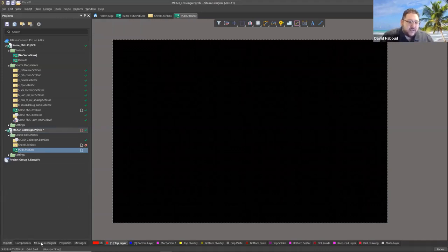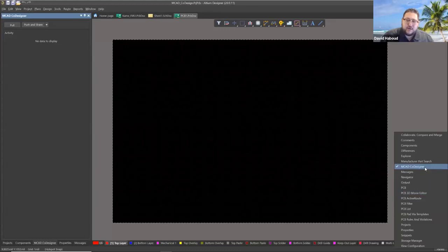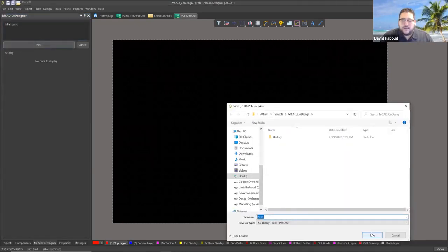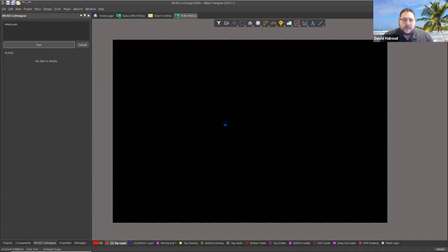Now that we have that done, I come over to the MCAD CoDesigner panel. You can go to Panels, MCAD CoDesigner if you don't have it up already. I'm just going to do push. If I do push and share, I can specify someone's email that I want to share that design to. But I don't want to send it to anyone, so I'm just going to say initial push, and post this. Of course, I have to save it for the first time. And I see it